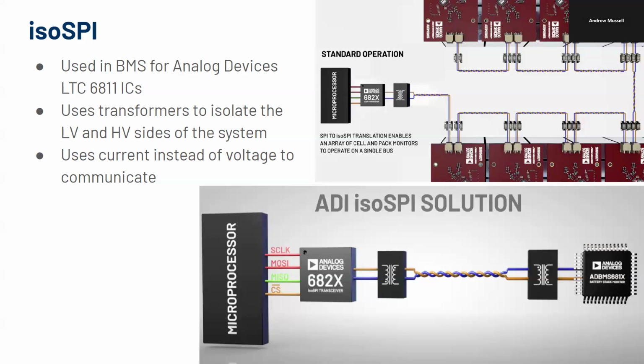If you get the magnetic field of both of them, those magnetic fields are canceling out as they twist around. So it'll stop the coupling between the two lines. It'll also stop external magnetic fields from messing with the communication line. Yeah, it's for signal integrity of coupled and differential signals.